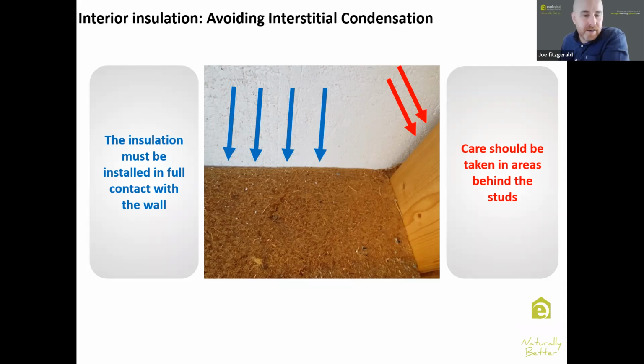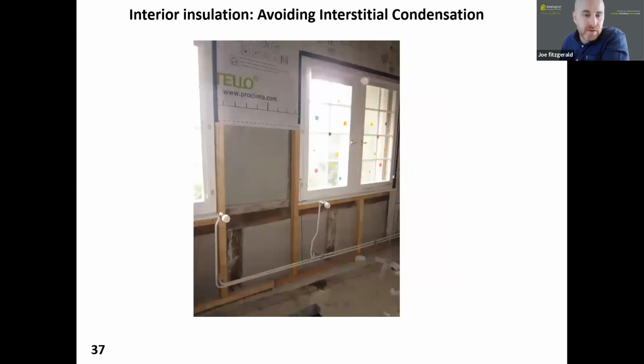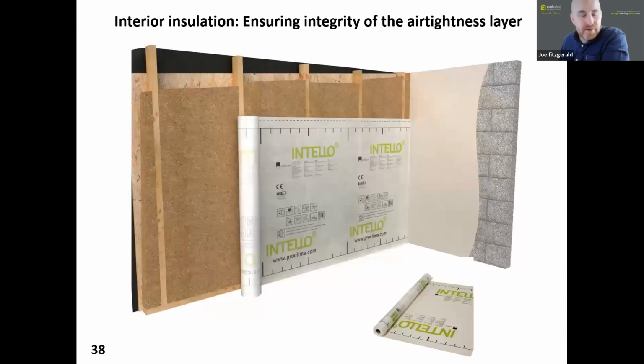insulation in behind it. That'll help thermally break it from the wall as well, to prevent excessive heat loss through the stud elements. There's a few different ways in which you can do it. You can build the stud with small noggins behind them, bracing it off the wall, or you can use sole plates and headers. You can install the membrane first and insulate after, or you can install the insulation first and put on the membrane after.